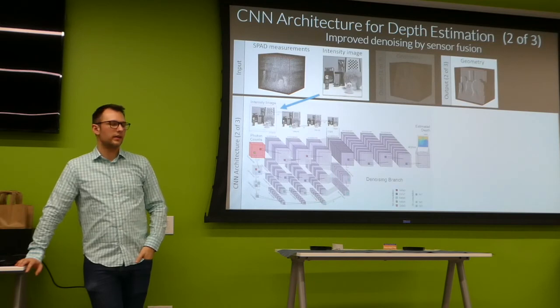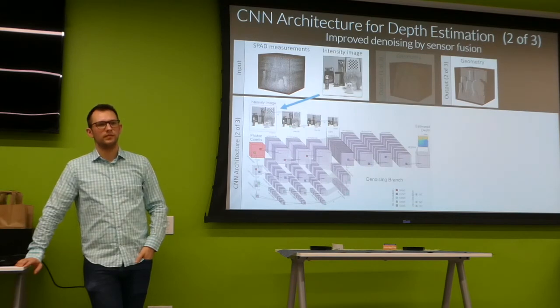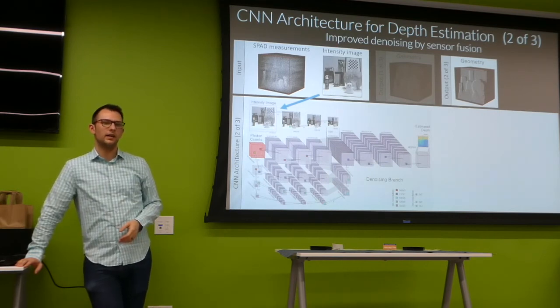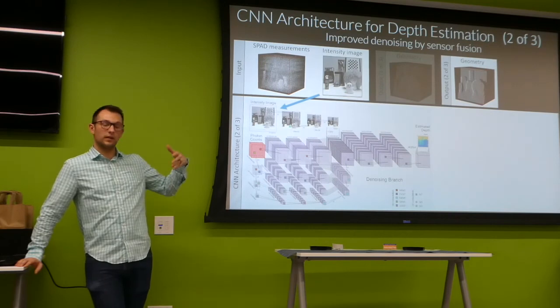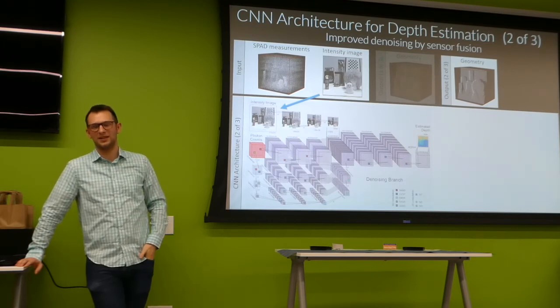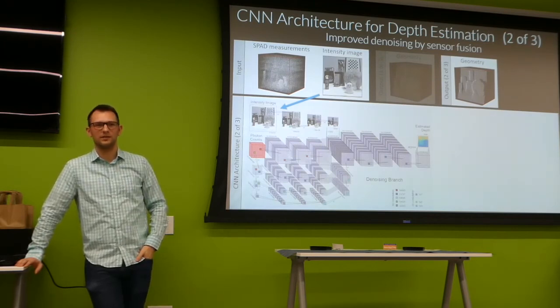Yeah, well, I think you could certainly do that. We haven't looked at this yet. I think it's a good idea. It might be easier to model what you would want out of something like a Velodyne because you can actually do that in simulation and then give that result to the software developers upstream and say, what if you had this information? Yeah, I think it's a great idea. And simulating the raw data, that's probably what you'd want to do, especially for us as we get closer to putting this on a car and then trying to demonstrate some of these things. I think we definitely keep that in mind. The hard part about that is you'd have to raycast for all of that data, and most of the simulators are actually not doing that now for performance reasons.